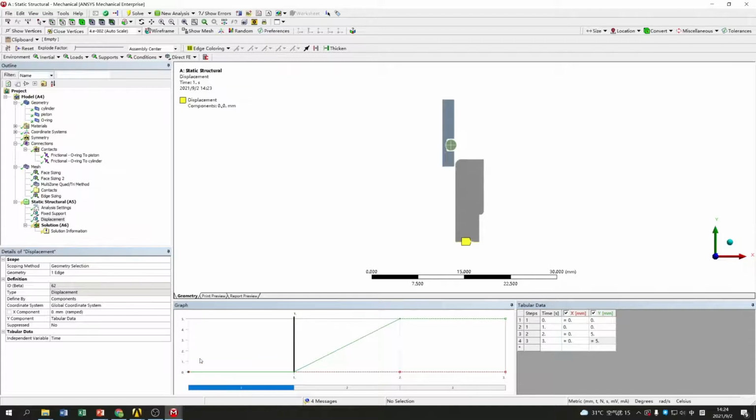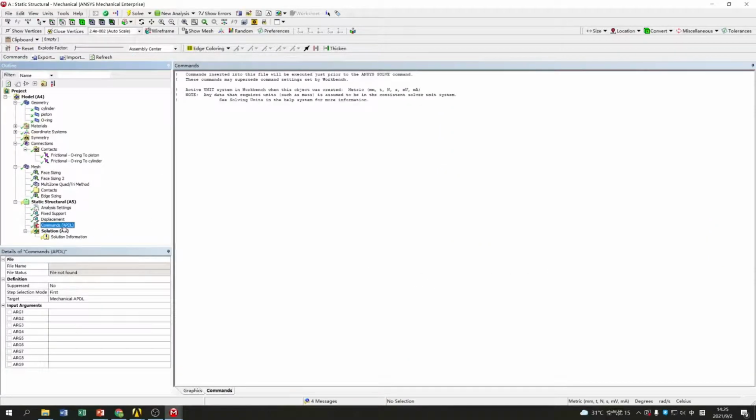And at the first step, we have to apply the pressure load. It's a little bit more complicated, and in ANSYS, we have to use APDL commands. Here, we choose the step selection mode to by number, the step number to the third number. It means the last step.